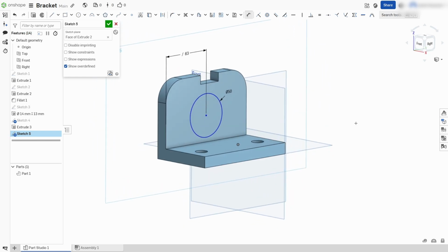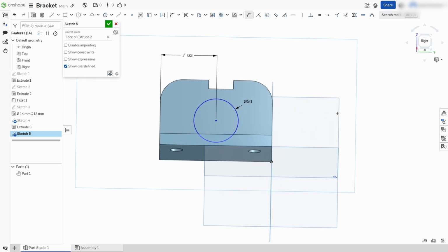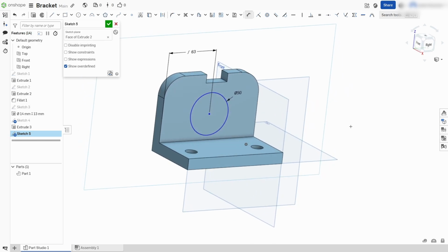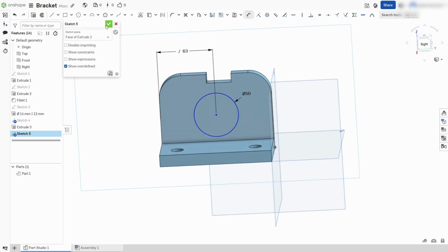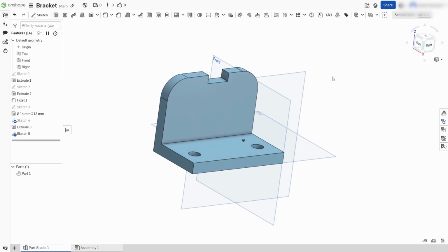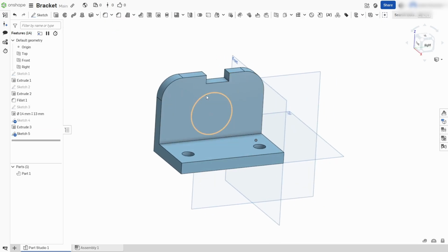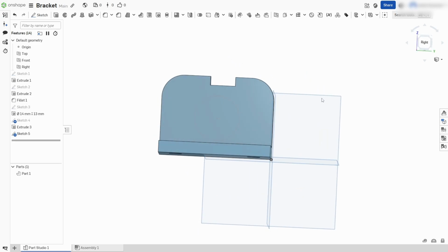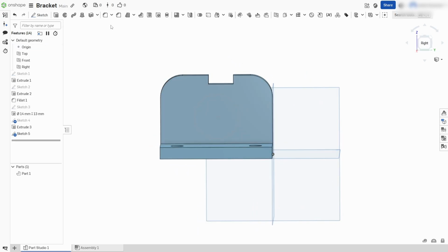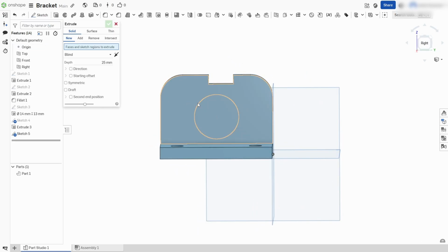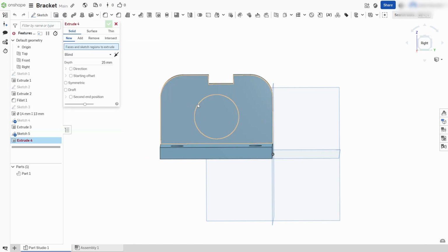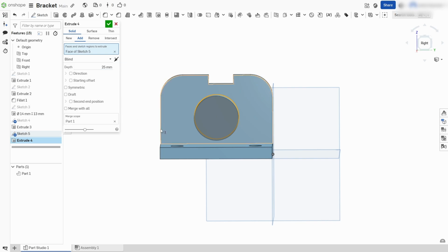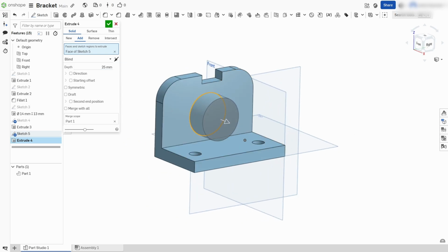So I'm looking at my sketch here. 126 divided by 2. I think this is off, but it's okay. We can keep going. Alright, I'm going to extrude this 38, so this should be, yeah, it looks centered. So I'm going to extrude it. Not the entire note. All I want is that one circle right there. Yep. And then we want to extrude this 38 millimeters out. 38.